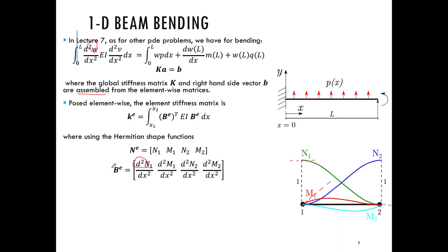And once we've got our B matrix, we can find our element-wise stiffness matrix and then assemble it into the global stiffness matrix. It is similar with the right hand side vector, but this time around the right hand side vector will be defined element-wise, the right hand side body vector basically. So I represented it with b omega right here. This omega stands for the domain or the body, right? So it contains the effect of the distributed load acting on the whole body.